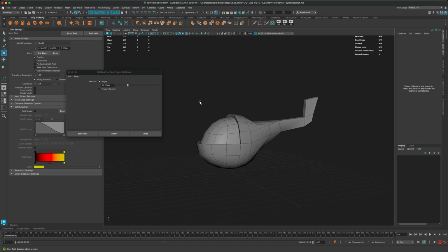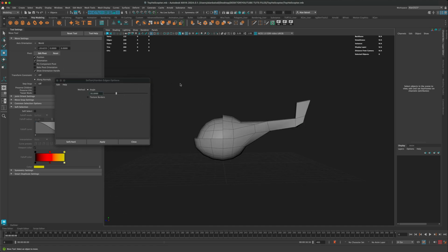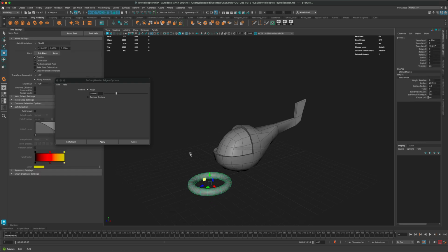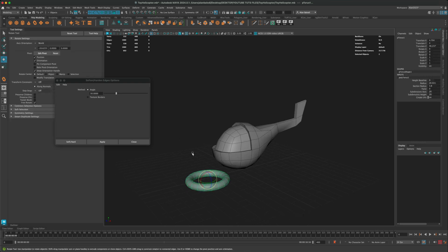So next, I'm going to go ahead and build the leg. So for the legs, what would be the easiest way of doing it? I think it's just to grab this torus here, and let's just create something like that. Grab our rotate, hold down the J key, and snap this 90 degrees.